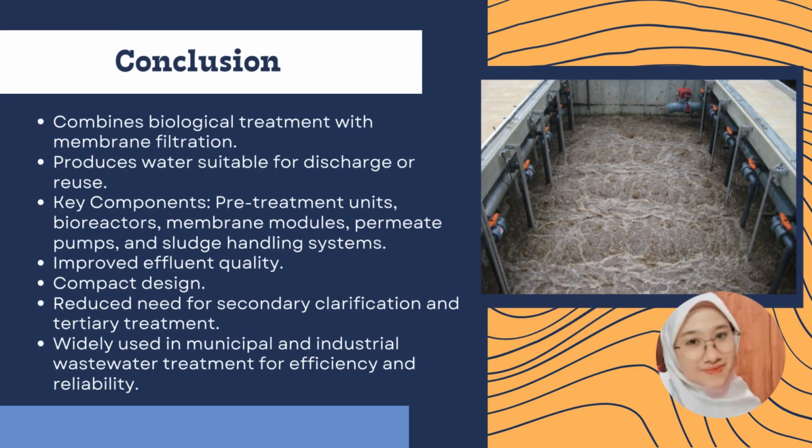In conclusion, membrane bioreactors (MBRs) are advanced systems that combine biological treatment with membrane filtration, resulting in highly effective wastewater treatment. They produce high-quality effluent that is suitable for discharge or reuse. The main components of MBRs include pretreatment units, bioreactors, membrane modules, permeate pumps, and sludge handling systems.